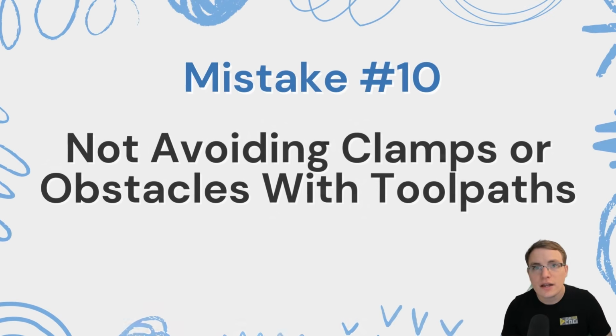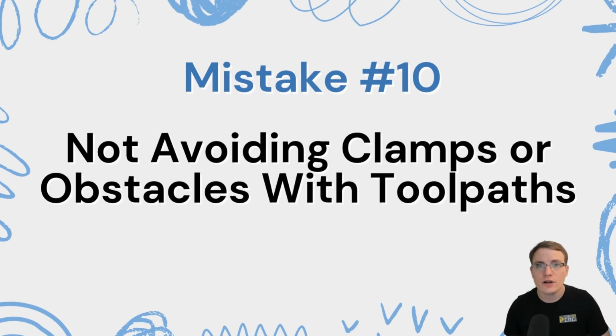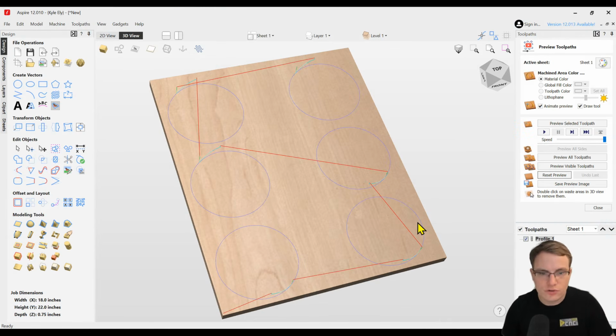And the final mistake that I see people commonly make with Vectric software that we're going to be looking at is not avoiding clamps or obstacles with your toolpaths. If you use clamps or screws or anything that holds down your material when you're cutting it out, you may have experienced this before or may have even seen somebody else experience this. Your machine sometimes will go right over top of those clamps and crash into them, and you didn't know it was going to do that, and then it breaks your bit or damages your machine or ruins your project or all of the above, and it's definitely not a good day when that happens.